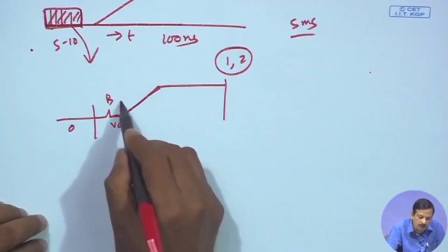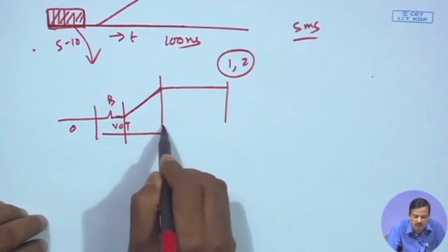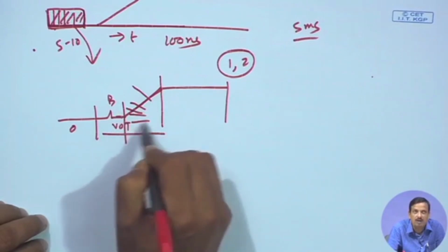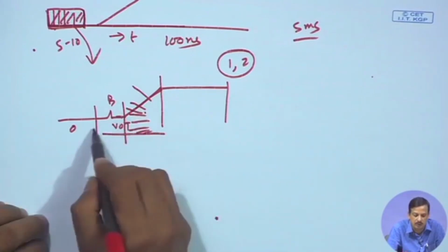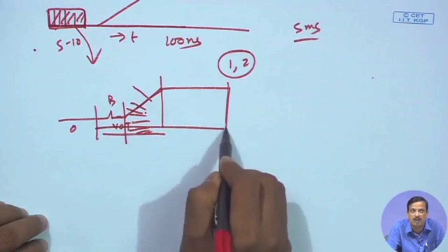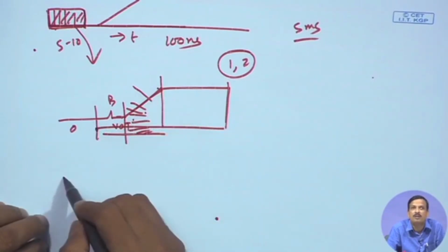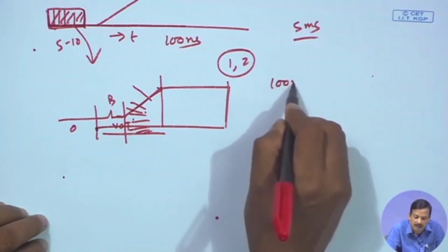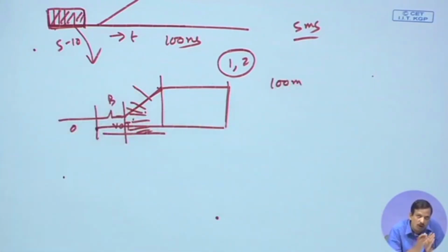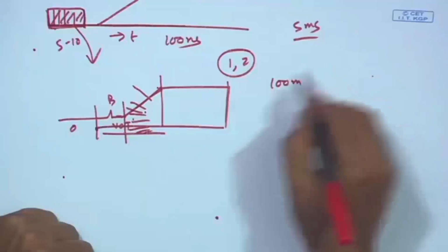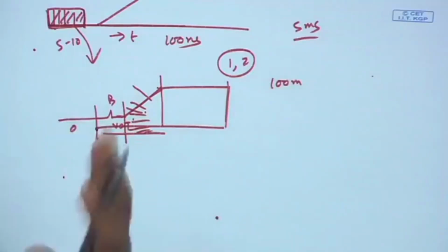So, the information which is very important, I lost this information, because it is averaged with the vowel and some part of the consonant. So, I lose the transitory part. So, with a small amount of signal there is a processing problem, and with a large amount of signal I lose the time resolution. So, what I want is an optimum length of the window, so that it does not affect so much.